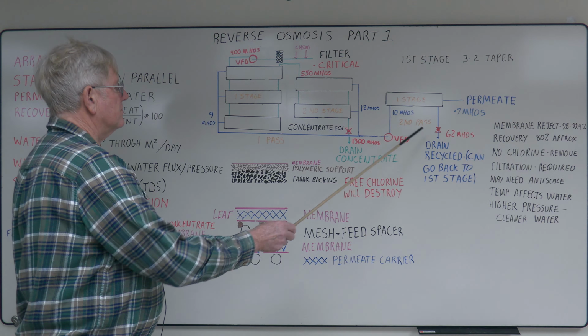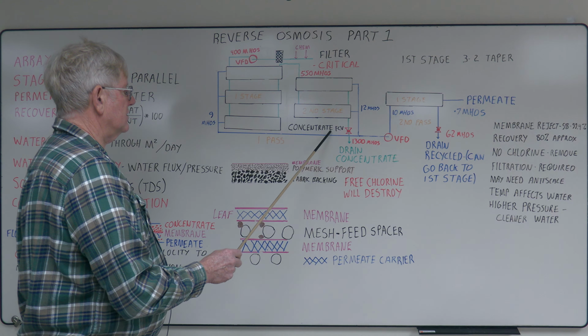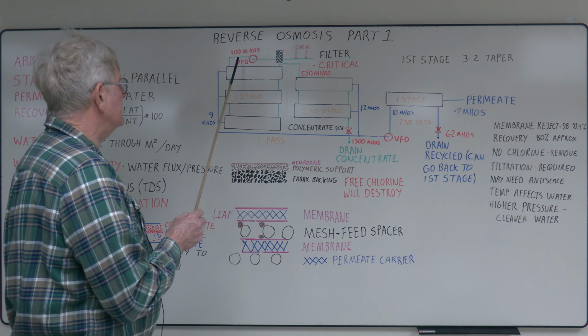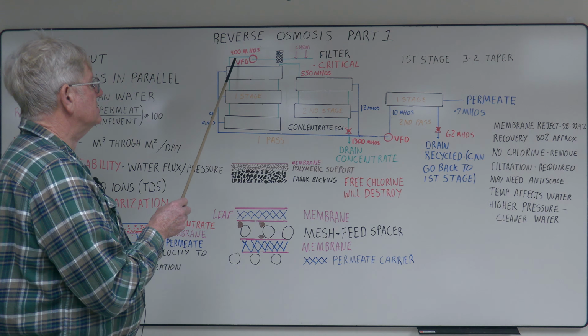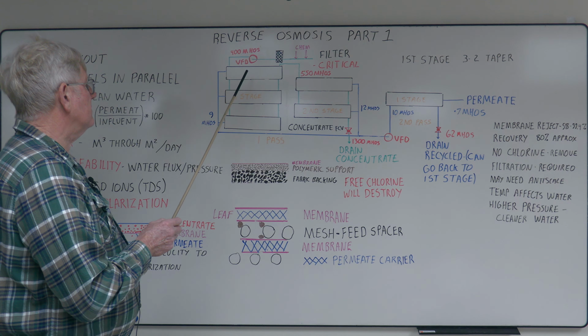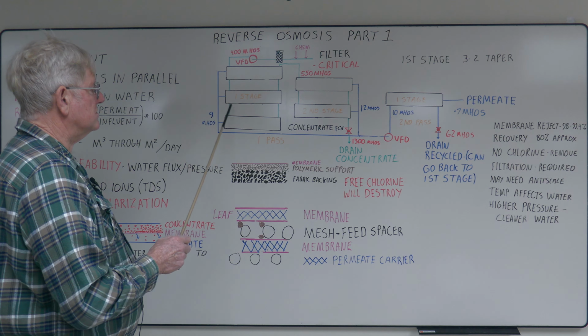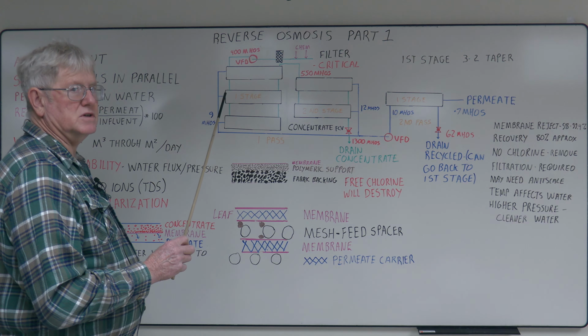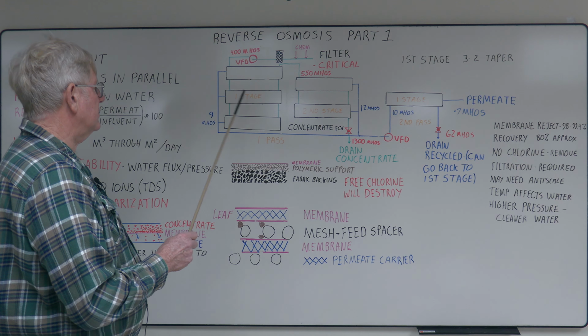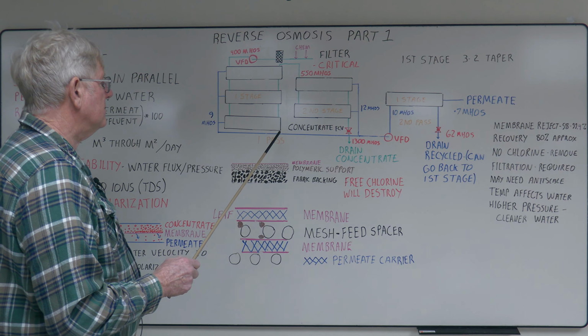With these valves set and left alone, one week you may run 78% on the VFD and put out 150 pounds to get 100 gallons a minute. Next week you may have to run 80 on the VFD and 160 pounds to get the same flow, which tells you your membranes are starting to foul. Either you're getting scale or you're getting plugging going on.